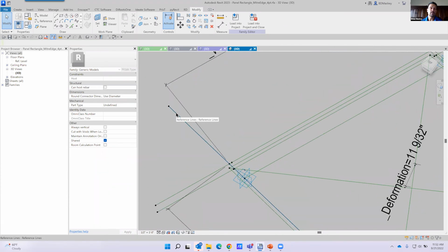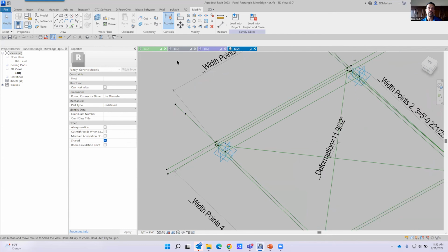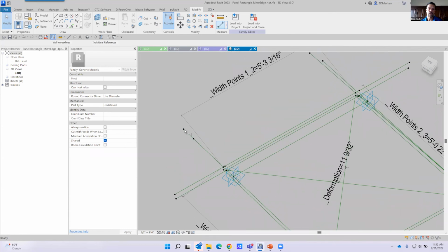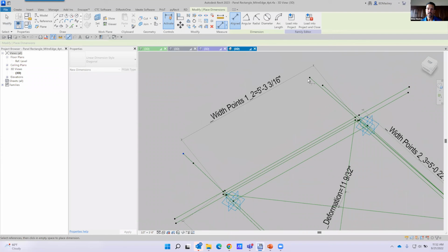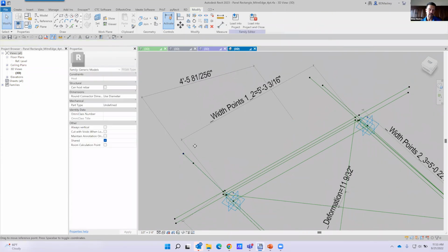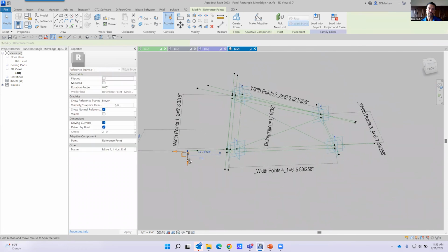I am just going to do a terrible example here, but I'm going to go ahead and set my work plane. Now I've got to go pick. Set work plane to be the end of this dot, right? So I'm horizontal to this dot. And then I'm just going to dimension from this node to this node and place it. Cool. So this one's being rotated, it looks like. Oh, that's right, because I worked this panel.